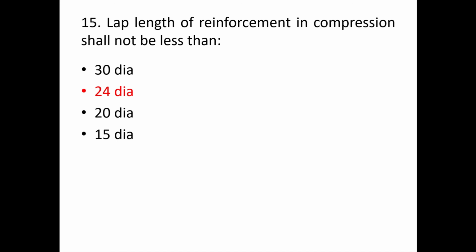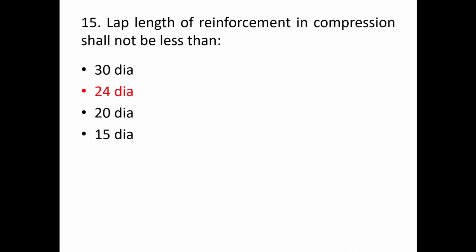And we know for flexural tension, it shall be greater of 30 times the diameter of the bar or development length. Okay. And for direct tension, it shall be greater of 2 times the development length or 30 times the diameter of the bar. Okay. So you have to keep in mind this clause of the Indian Standard 456/2000. Okay. So this is our last, and I hope it is clear to all.